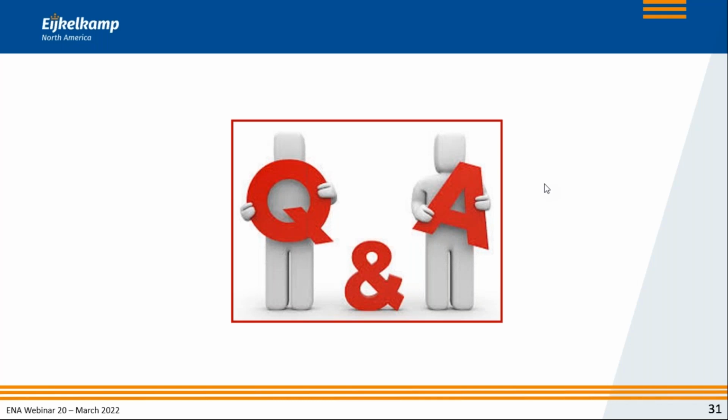Well, the problem is that all that may be part of the whole thing, but as you already put it in your question, you talk about settlement. And we have seen this kind of increase in tip resistance without any settlement in the soil, without any change in pore pressure. So it's a complex issue that is really not all that easily understood or explained.